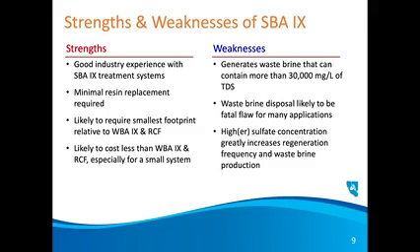It does generate the waste brine that has thousands of milligrams per liter of TDS, and I just picked a 30,000 number as a minimum. Disposal will likely be a fatal flaw for a number of applications. And higher sulfates would greatly increase the regeneration frequency and make it even more of a problem to be able to manage that salt disposal.